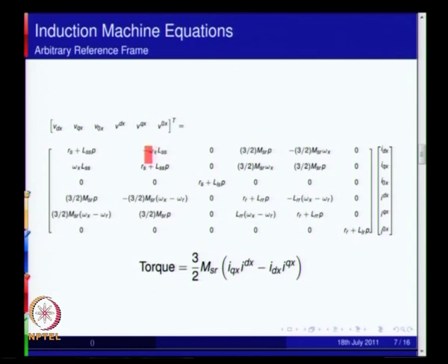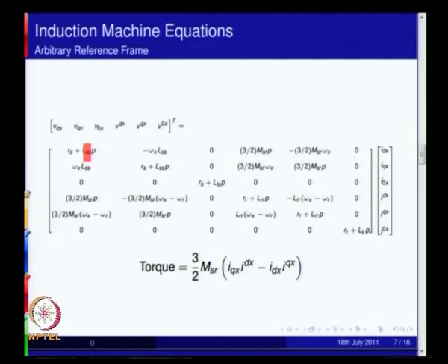Now it has an omega x into LSS, and similarly here you have another speed EMF term which arises due to the rotor q axis term, and this is a di by dt term arising due to the same coil on the same axis of the rotor. So you have di by dt terms for the self flow of current and then a mutual current flowing along the same axis. This is multiplied by idx, this is multiplied by iqx, this is also a qx term.